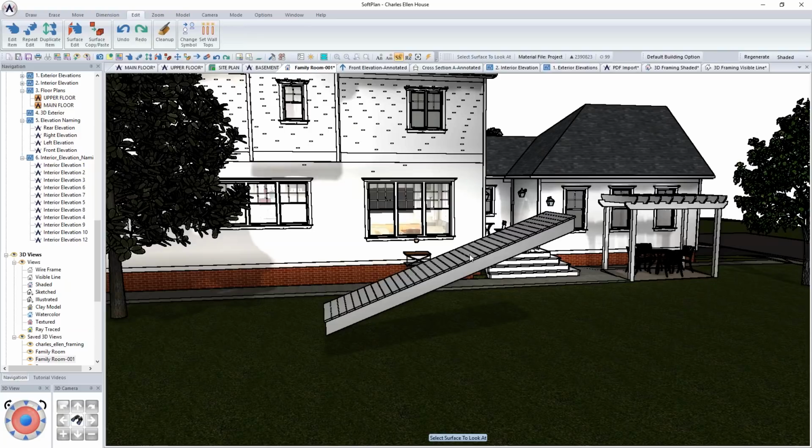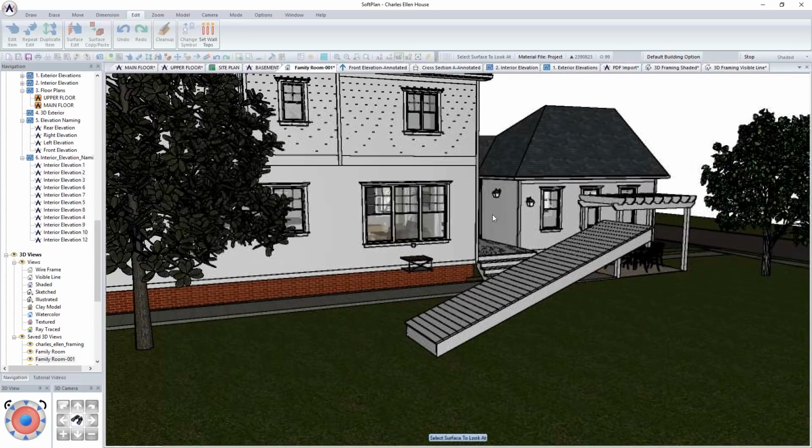I know some of you had gotten creative. I've seen on the user forums where you created this as stairs and you kept stair stepping it up, 1/8 of an inch at a time and so on in order to create that sort of option. So now it's just simply a matter of using the Draw Deck Ramp tool, give it the rise, and this is going to automatically calculate this for you and give you the bill of materials.